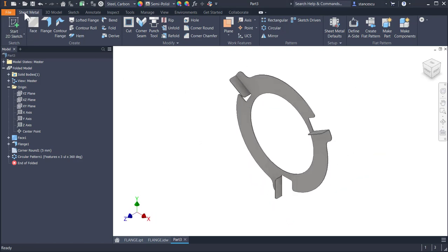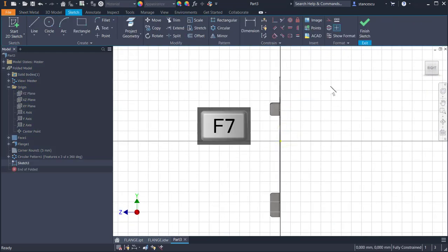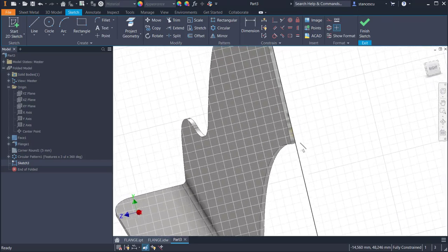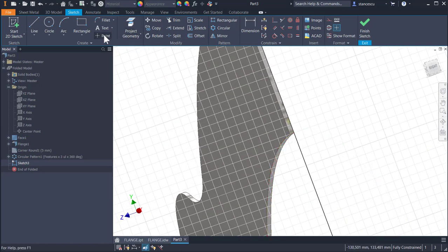As you can see, I use the environment sheet metal. Yes, all these tools are associated with the sheet metal. I try to use sheet metal to create that deep drawing in the middle. Let's see what happens. I select this plane, F7 to see inside. I project this generator of a flat cylinder,